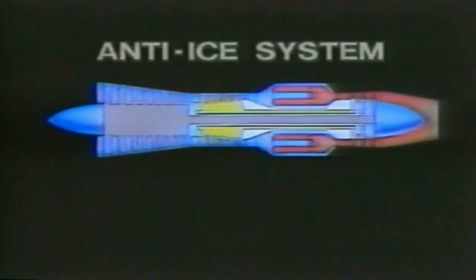But on the airplane, everything goes in the inlet of the engine. The rain, the snow, the ice. That brings up the necessity for our anti-ice system, number 8 on our list. You see, with atmospheric conditions just right, ice can form on the inlet vanes, nose cone, and even on the first stage of the compressor. A buildup of ice could distort airflow to the point that compressor stall is inevitable. It's easily prevented, however, with an anti-icing system.